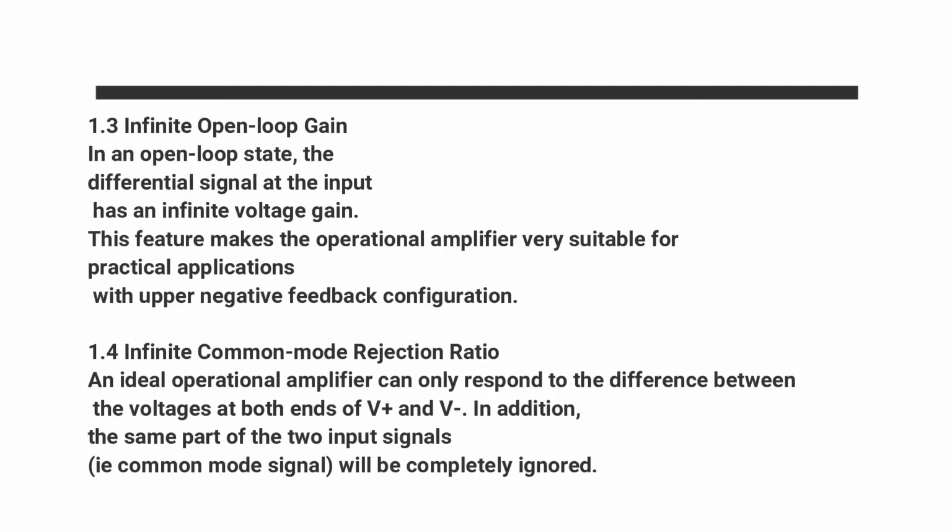Another OP-AMP characteristic is infinite open loop gain. In an open loop state, the differential signal at the input has an infinite voltage gain. This feature makes the operational amplifier very suitable for practical applications with negative feedback configuration. Next, infinite common mode rejection ratio. An ideal operational amplifier can only respond to the difference between the voltages at both ends, V plus and V minus. In addition, the same part of the two input signals, the common mode signal, will be completely ignored.